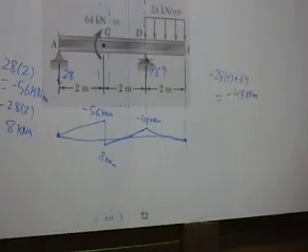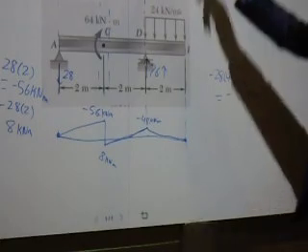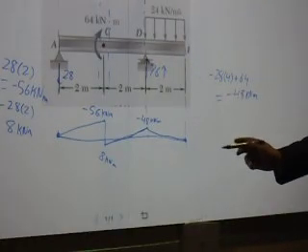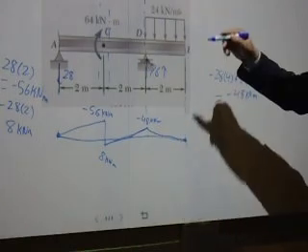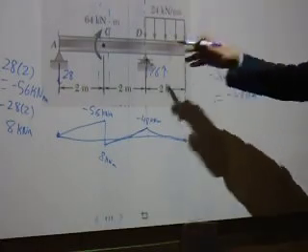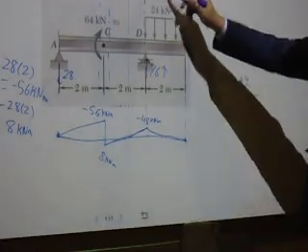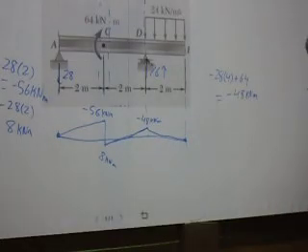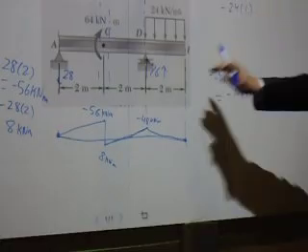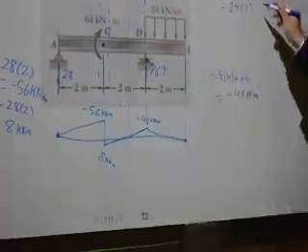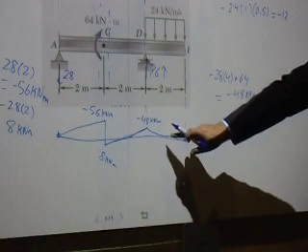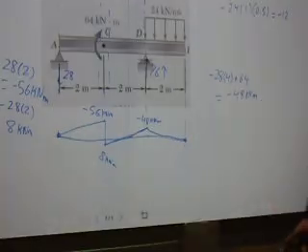Okay, right? You can take a moment in the middle, take a section in the middle and see the value, but because I solved it a lot I'm telling you it's this way. Other than that, if you want to take a section, let's see, take a section here and look there. The easiest thing in the world, by the way: take a section in the middle of the cantilever and look there. What will I see? I'll see negative 24 times 1, because this distance here is 1, times half. So this is negative 12. Negative 12 is less than half of the 48. Okay?